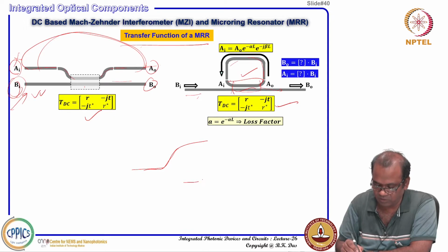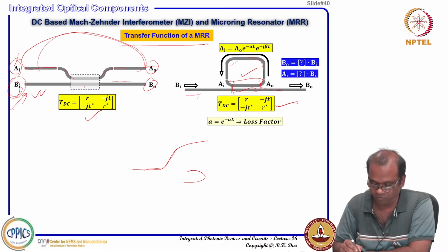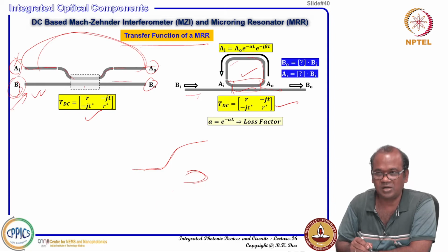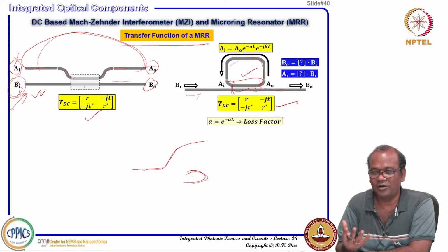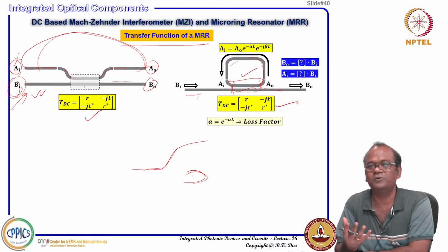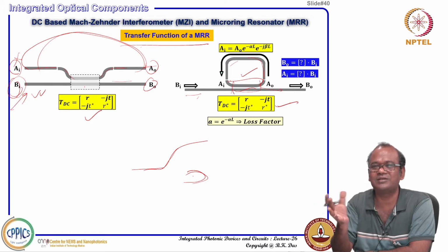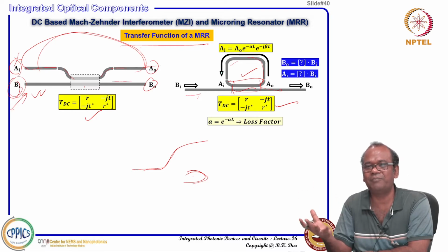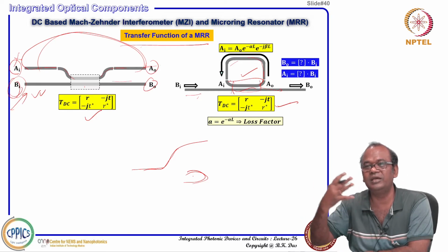But if you make a quick, sharp bend in the structure, in the bend region you can assume there is a strong perturbation because of the bend-induced perturbation, and that perturbation causes some loss of the orthogonality condition. So power exchange can take place, and the guided mode can radiate power into leaky modes.